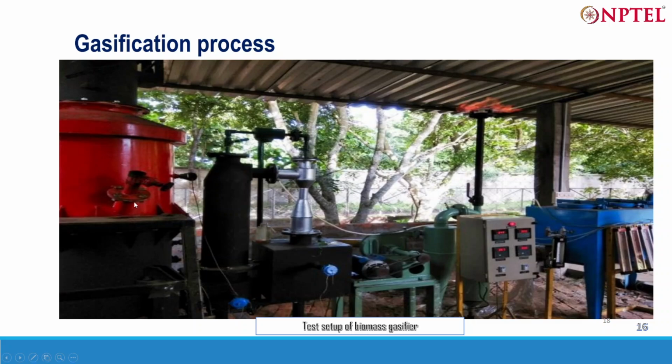Another thermochemical conversion route is the gasification process. In gasification, we are not working in an inert atmosphere; we are basically using partial oxidation. If biomass has carbon, hydrogen, nitrogen, sulfur and oxygen, the CHNSO elemental content, we can derive a CHNSO formula. Based on that formula we can have a stoichiometric ratio for incineration or combustion. When you provide oxidant less than that stoichiometric ratio, that goes into the conversion of biomass directly into producer gas.